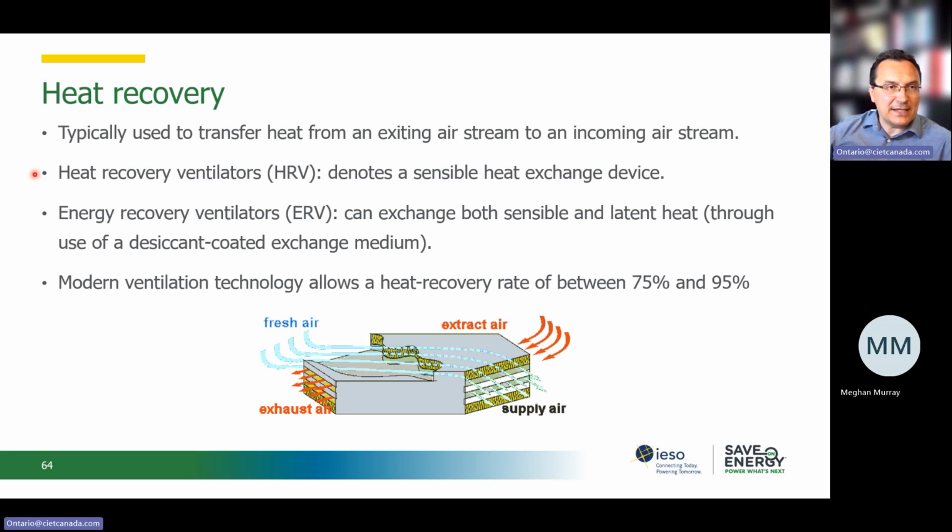We have heat recovery ventilators. The difference between heat recovery ventilators and energy recovery ventilators in the industry is just what type of heat we are recovering. So for heat recovery ventilation, we are focusing on a sensible heat. And for energy recovery ventilators, we focus both on sensible and latent heat. So basically, we recover the moisture from the exhaust there as well.